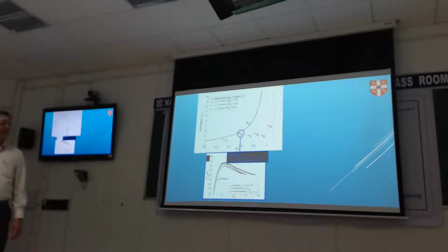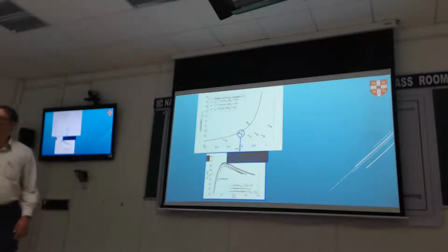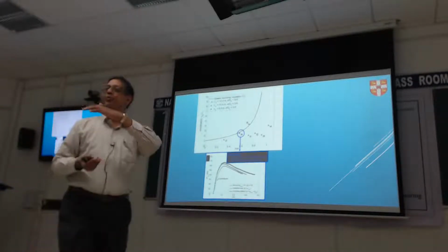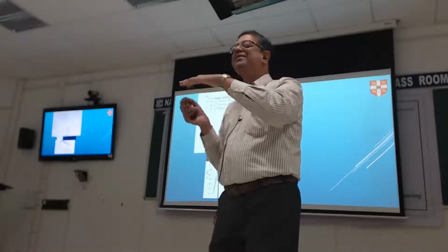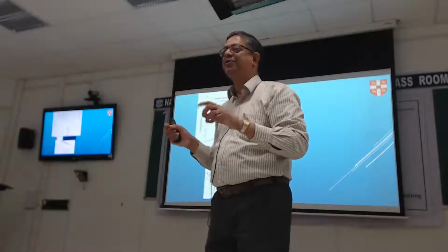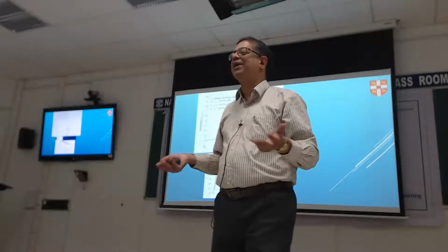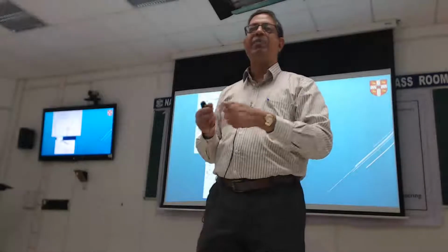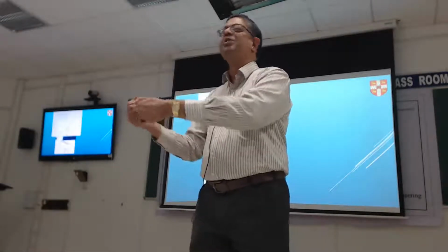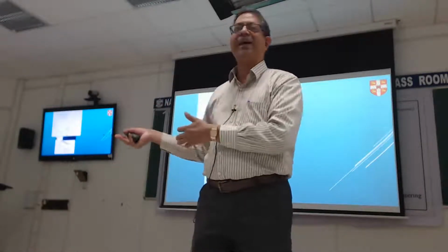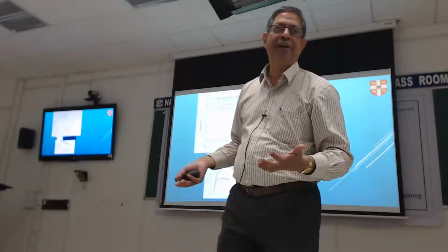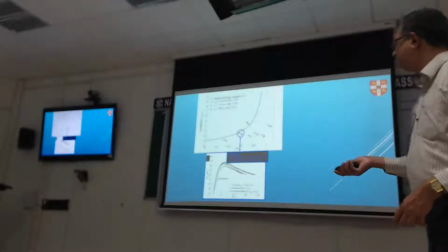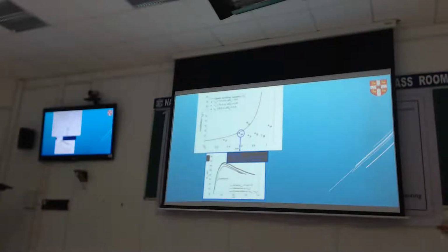Little effect of soil resistance and pile dominated responses. So these are short piles. Therefore, they don't move very much horizontally, which means whatever the soil is there next to is not doing very much, and that makes sense. You will only demand the soil to oppose your motion if your pile wants to go away somewhere. If it's not going anywhere because it's a short pile, there's no effect. It's a very small contribution from the soil.